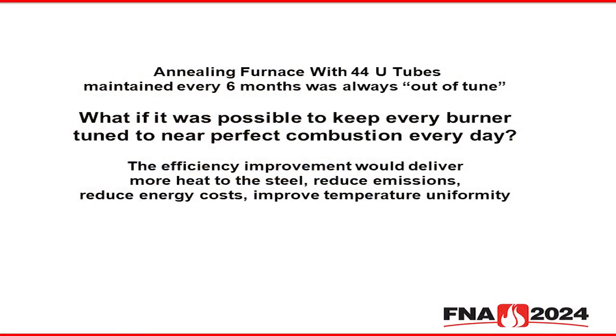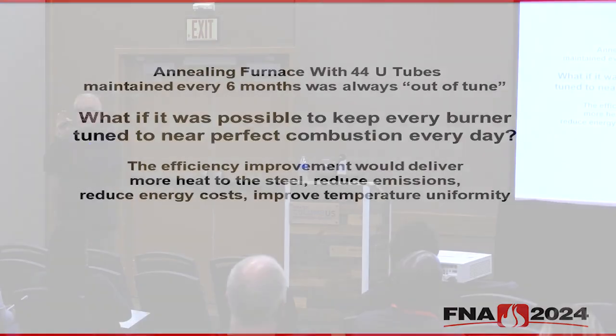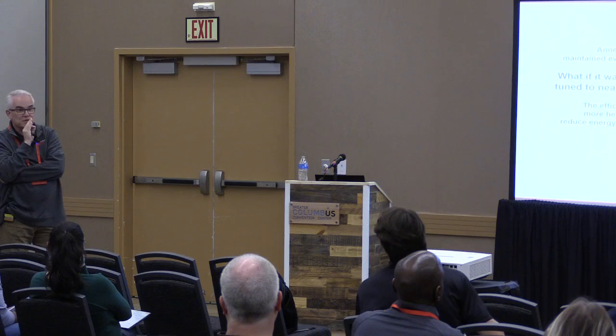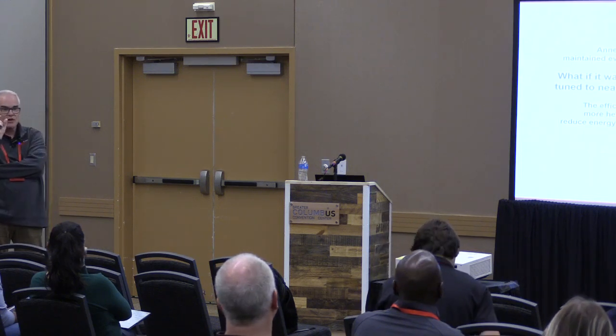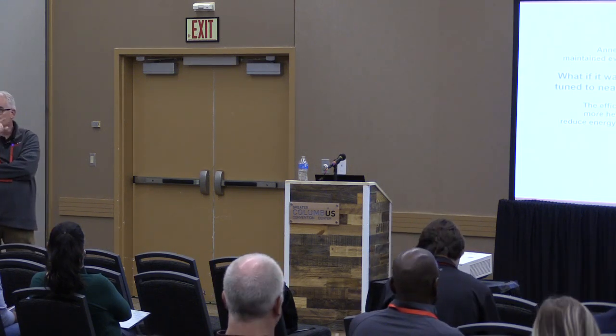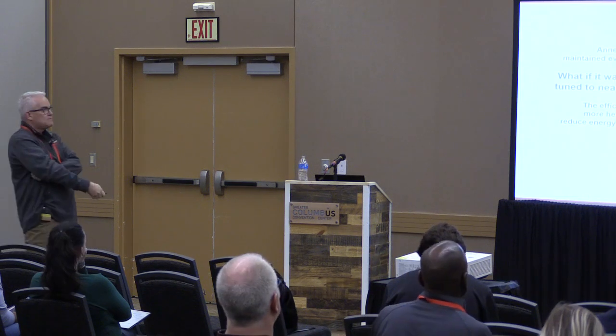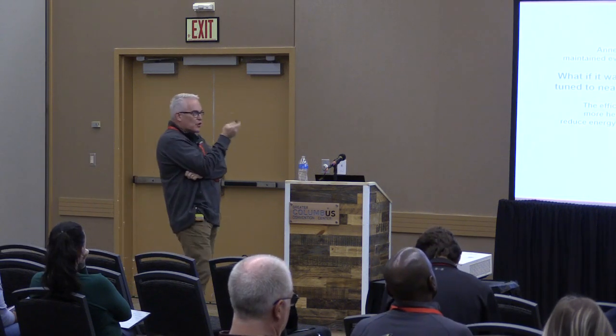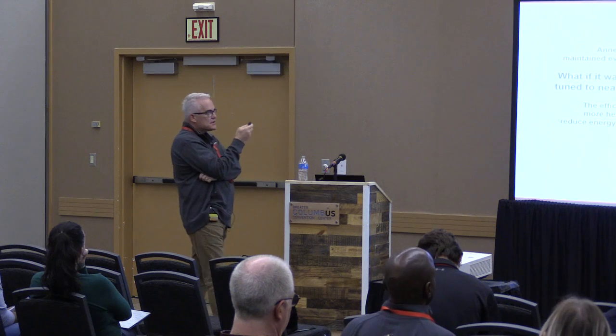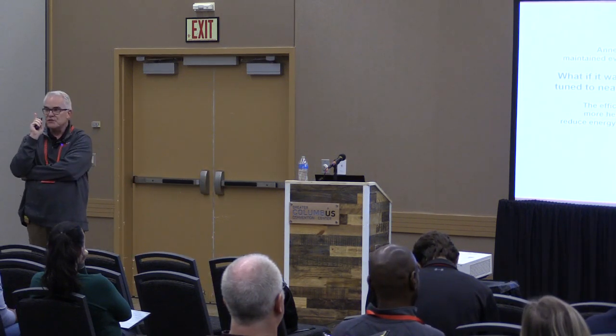Something to think about. But what if it was possible to keep every burner tuned to, again, 3%, 2%? The truth is if you actually could do it every day, you could start getting a little closer to 2% than the 3%, because as it drifts, you'll catch it before it gets you in trouble. The efficiency improvement would deliver more heat to the steel or aluminum, reduce emissions, reduce energy costs, and improve temperature uniformity, and it would be safer for your employees, and you wouldn't need as many maintenance guys running around trying to keep the furnaces maintained.